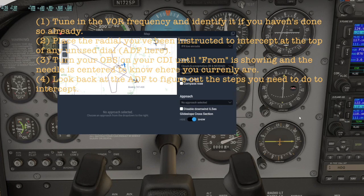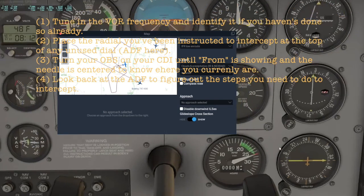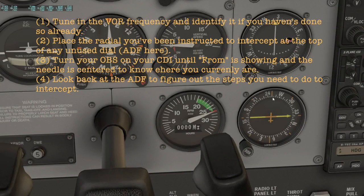So first thing, you're going to tune in and identify the station you're supposed to intercept the radial for. Once you do that, you tune in, you identify, you can listen to the Morse code, and you make sure that it's operational. You go ahead and put the radial that you've been instructed to intercept on the top here. And once you do that, whichever it is, let's say for example you're instructed to intercept 210 inbound or outbound, it doesn't matter, you just put it on the top.